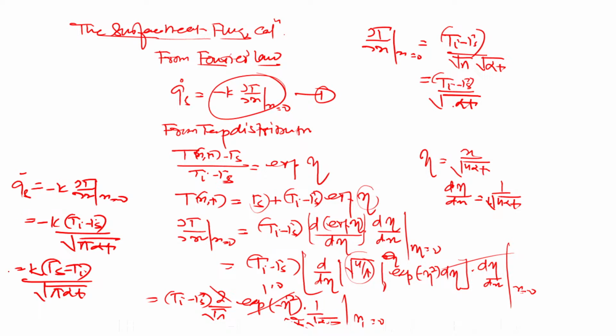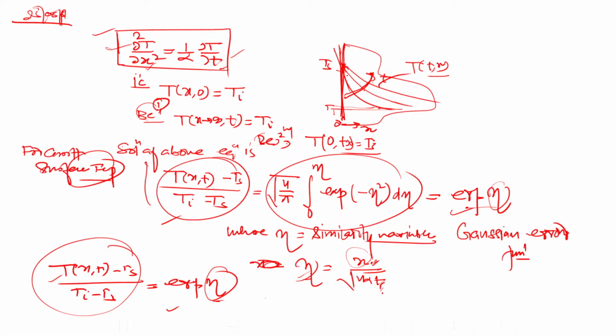So this is the flux that we get here, and the flux is found to be a function of time. The question which has been asked here is, in the constant surface temperature condition, how the flux is going to vary with time. As time t increases, the flux decreases. Or you can say dT upon dx, the temperature gradient at x equal to 0, is inversely proportional to time. Yes or no? And you can see here, I have drawn it in the last lecture. As time t increases, the flux is going to decrease. The temperature gradient gets decreased, yes or no? You can see.